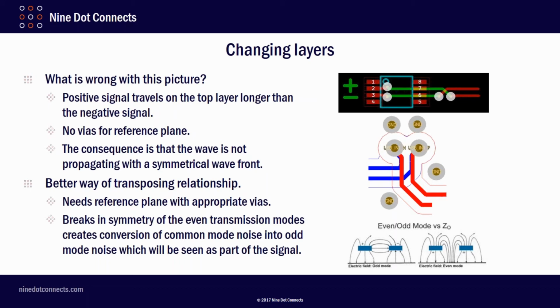One thing that I've noticed over the last 10 years or so when talking to people about differential impedances is they seem to not contemplate, or keep in the front of their mind, the need to monitor the common mode impedance. So if you look at the spec on, let's say, USB lines, and they say 90 ohms differential, it also includes a common mode impedance or a single-ended impedance. That's because there are still going to be fields created in this even mode of transmission.